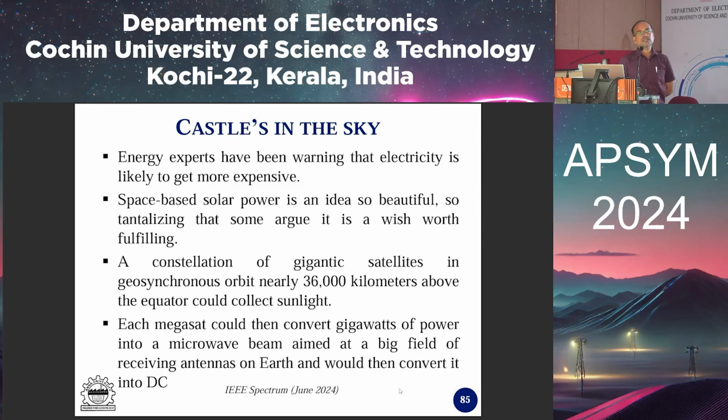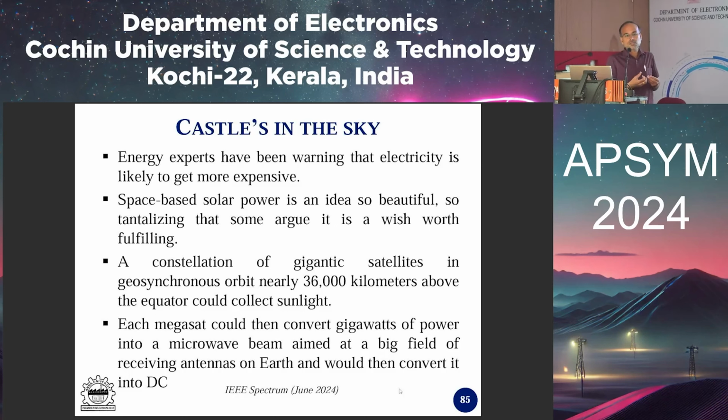If we go for drones, we need to make sure that the unit cells are much closer to each other as well as much smaller. That's where the angular independency as well as the stability lies. These can be printed on some fabric or sheet, so the weight can be reduced. Yes, we have tried it once on plain white paper. We pasted some conductive inks and it provided 15 to 20 dB of attenuation. That is possible. Again, the temperature and deployment conditions we have to test, and the moisture content also plays a very important role.